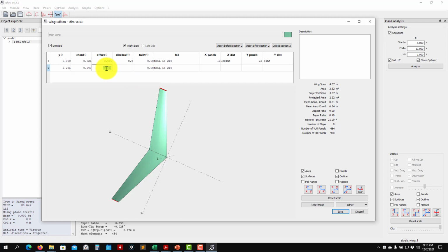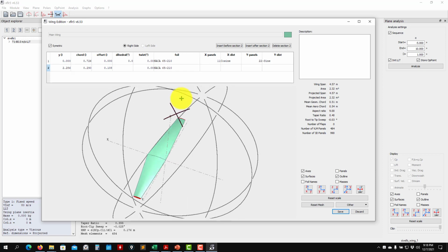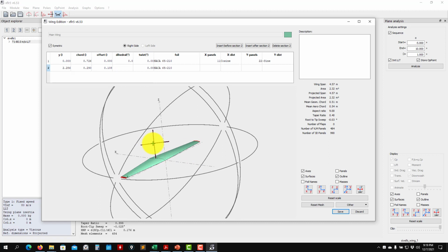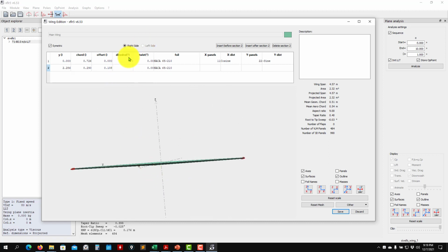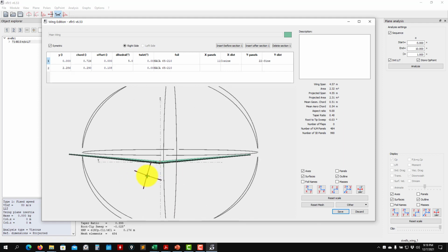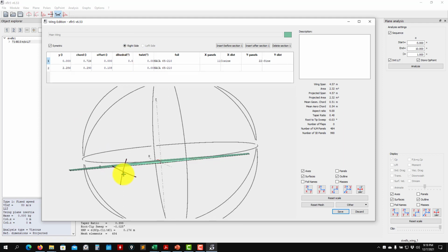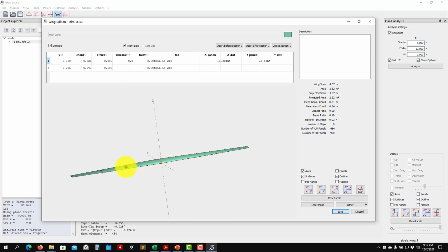But in our case, we saw that we're only interested in that for high speed, and we're not in high speed. So here we're keeping the original design. Then the dihedral: this is the incidence angle of the wing, not the angle of attack. Be careful. This is the design angle, the angle for stability. You define this one. For us, we have seen that this will change the lift a little bit, but it's not a problem, and this angle doesn't modify the output of the LLT.